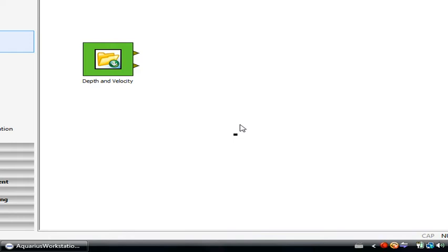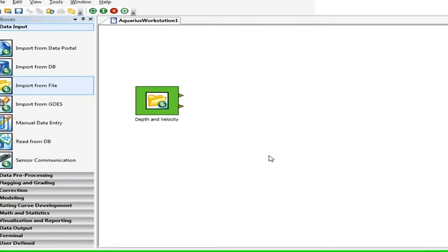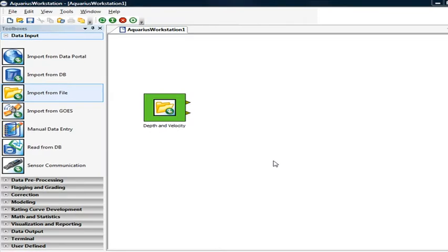The other way of doing a flow calculation is monitoring the flow velocity, usually using an acoustic Doppler or some sort of flow velocity meter in the pipe as well. And this could be more useful when we have backflow conditions or some sort of control methodology that's not strictly the pipe itself, when we don't have prism flow down the pipe. I'm going to start by doing the calculation using the simple Manning equation using prism flow down that pipe.